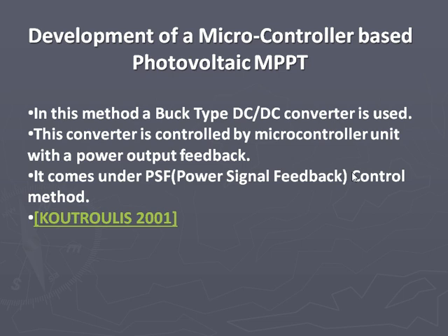And so your idea is different from power signal feedback because your idea is not using a buck boost converter to try and create the DC level of the mains. So your idea is to try and do synchronization by controlling the tip of the rotor. Yeah. And so you do that by adjusting the pitch of the blade. Yeah, pitch of the blade, and actually it's like a control unit which is moving between TSR mode and hysteresis mode.